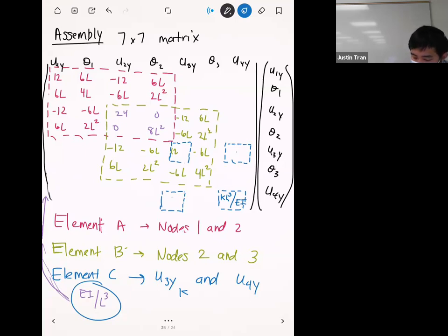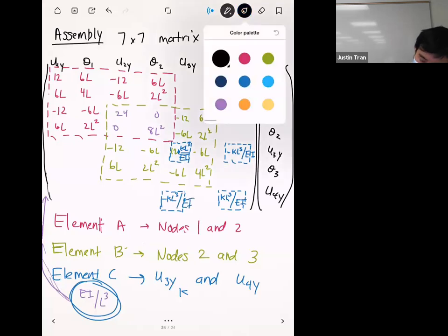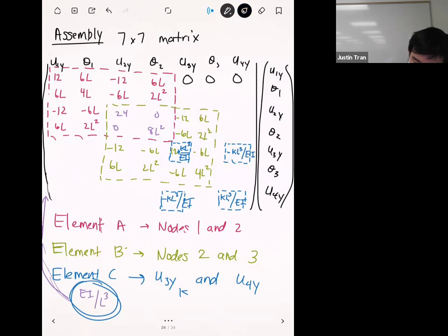And so when you multiply this whole entry here in the bottom right by the factor out front, you just get K, right? And that's what you should get, because the spring is only contributing just K. All right, so let's go ahead and fill in the rest of this. It's going to be a little bit tight in here. And so it's going to be 12 plus KL cubed divided by EI. Here we have a minus KL cubed divided by EI. Then here we have minus KL cubed divided by EI. And of course, everything else here is zeros.